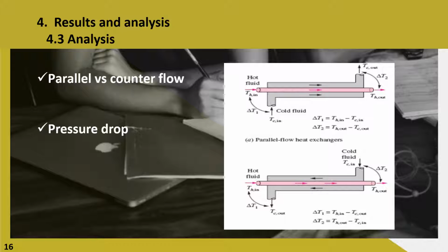When it comes to comparing the different flow arrangements, parallel and counterflow, it is evident that experimentally and theoretically the results for all the variables obtained are not extremely different from one another. There are some important differences that should be highlighted, such as the fact that with the parallel flow arrangement, the heat transfer is more efficient than with a countercurrent flow arrangement. It is also important to observe that the pressure drop in shell and tubes is lower when the fluids flow in parallel. The pressure drop in the shell and tubes can be considered negligible since the losses are 1 to 5% in the corresponding diameters.